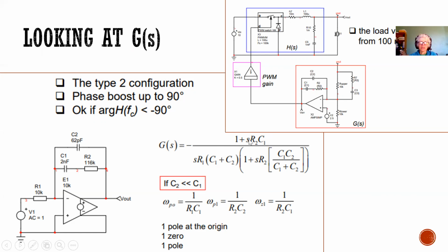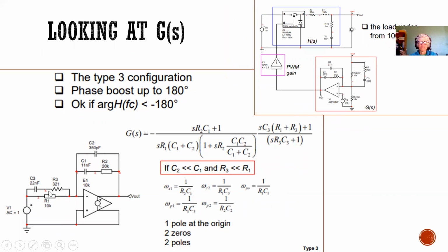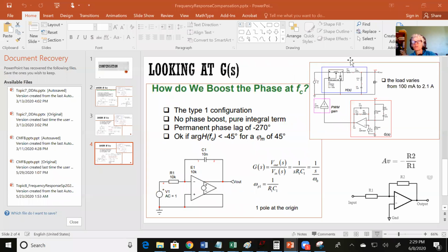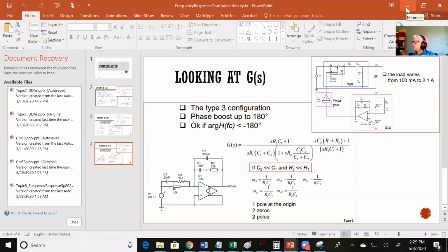And you can keep going on that. You can have an RLC network on the input as well as in the feedback to do that. But yeah, it's all about moving that dominant pole over, so you don't violate Barkhausen's.